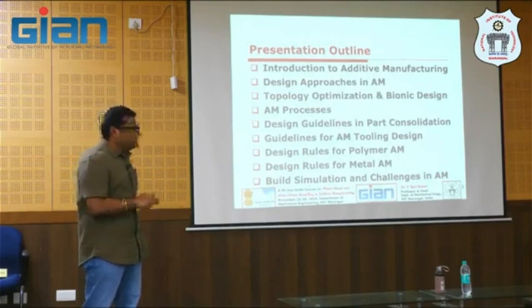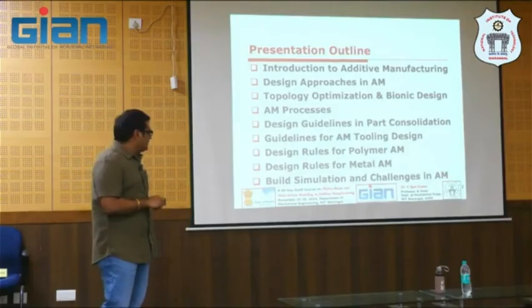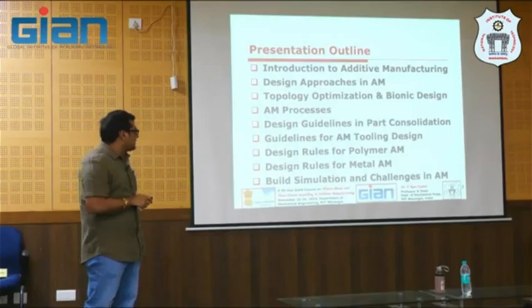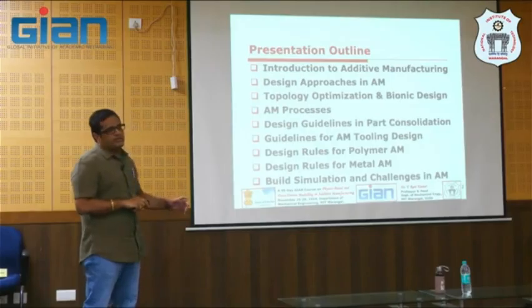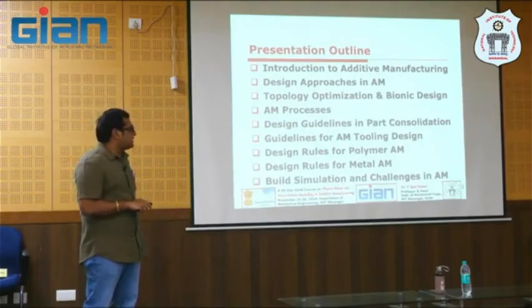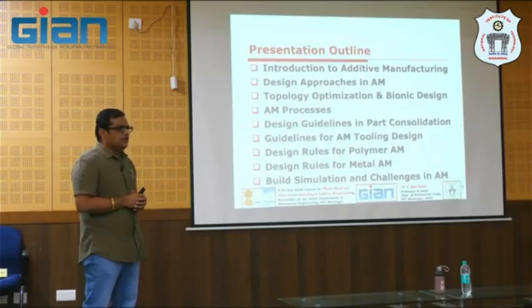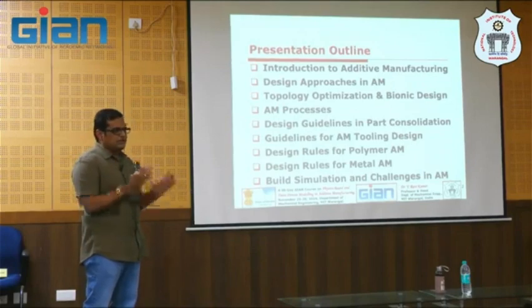And AM processes, yes, the previous speaker has given enough introduction on the working principles of AM. Another advantage or unique capability of additive manufacturing is part consolidation, of which we have seen one case study from GE, the LEAP engine fuel nozzle, right? Where you can consolidate several parts in an assembly or a sub-assembly.